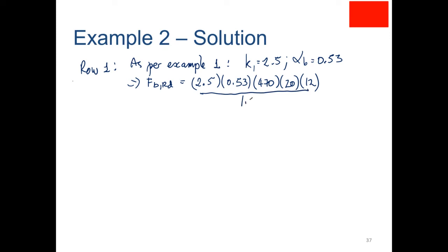This is 12 because it's the 12 one that dictates it, divided by the partial factor of safety of 1.25. That's 120,000 newtons, which is 120 kilonewtons.